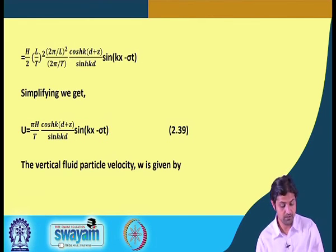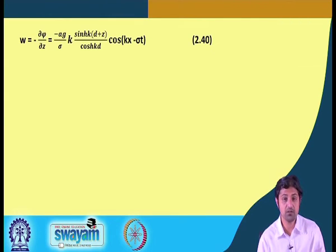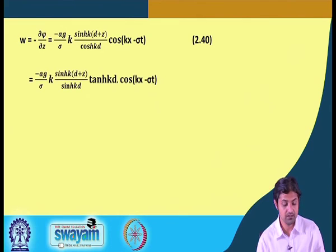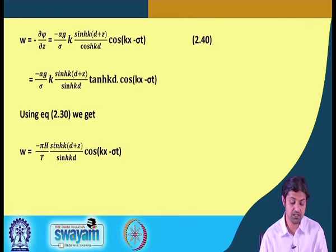All right. And similarly, we can find the vertical fluid velocity is given by minus del phi del z. Okay, and therefore similar substitutions will give us minus pi H by T sinh k(d plus z) divided by sinh kd.